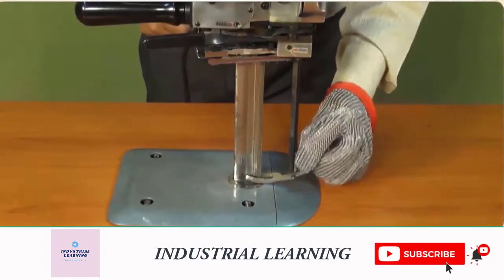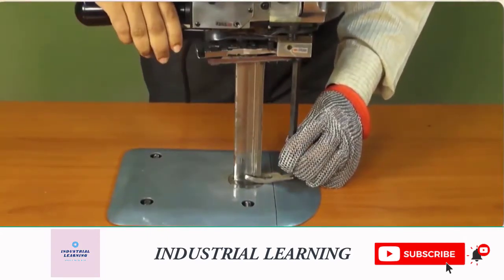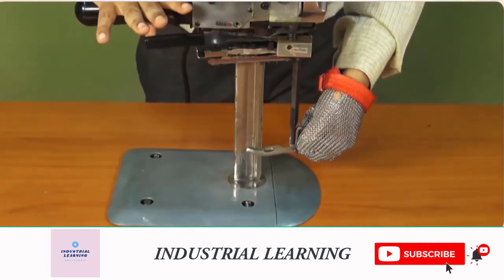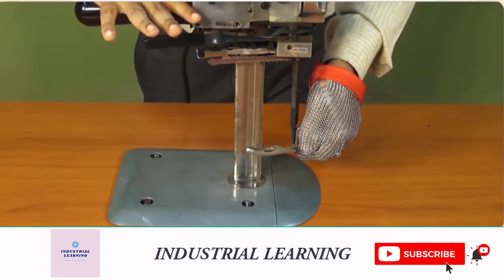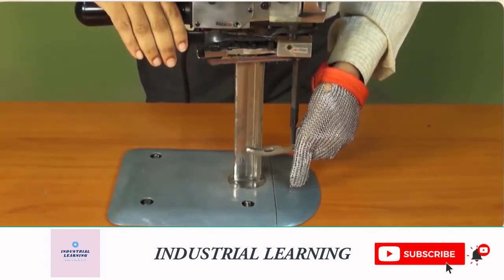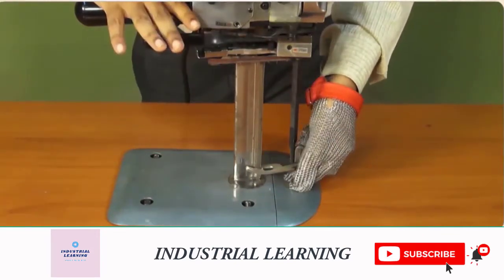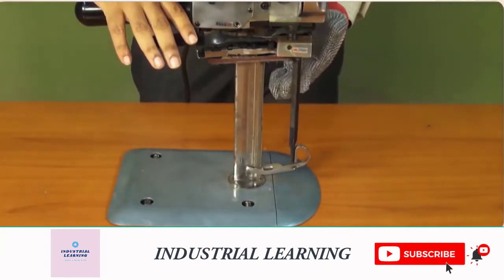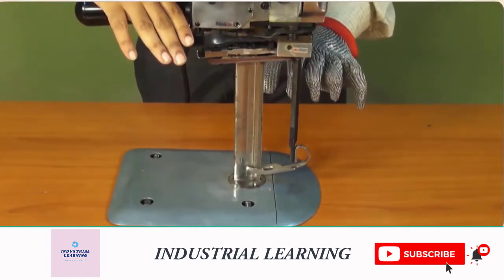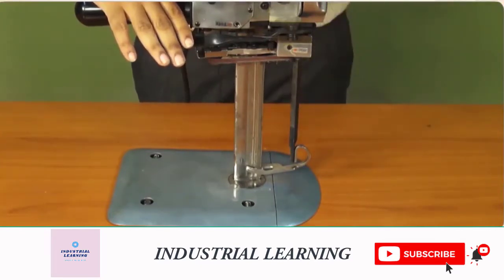This is the knife guard. To lift the knife guard, we have to press this handle, lift it upwards and leave the handle, so that the knife guard gets set in position. Or if you want to lower it down, again press the lever, make it down and leave it. The function of the knife guard is that it has to go and sit on top of the lay to provide a firmer grip to the machine on fabric.